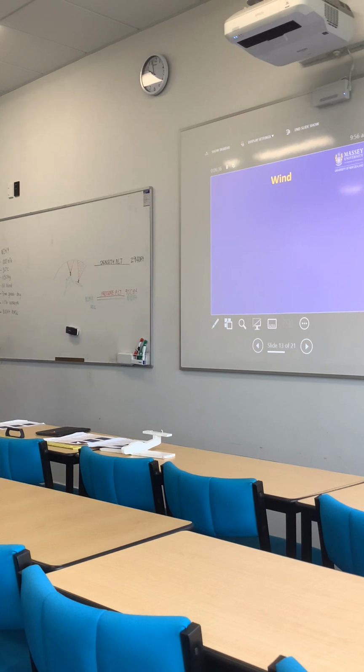Now we talked a little bit about wind in previous briefings, climbing and descending briefing. So what do you remember about that? You could pose a question about that, see if they remember why we take off into a headwind. It's okay to use extremes to illustrate the reasons here. I think I used extremes when we did the climbing and descending briefing. So imagine we're lined up on the runway for takeoff and there's a 60 knot headwind. That's our rotation speed. So we go through to full power and we get airborne on the spot. We would need no runway at all to get airborne.